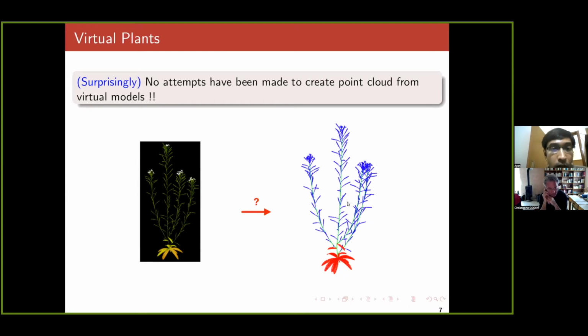It depends on how you model your plant, and whatever your application demands, you can generate the point cloud data accordingly. For example, if you want semantic segmentation, then this type of labeling is sufficient. But if you want instance segmentation, where each instance of the same object has a different label, then you probably need to customize it more. That means you have to have a different label for each of these organs. These are all possible to do with this type of model.